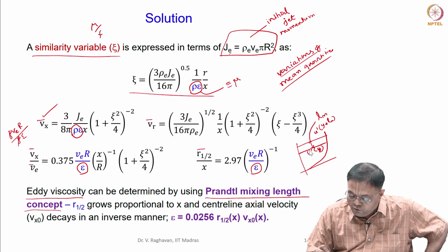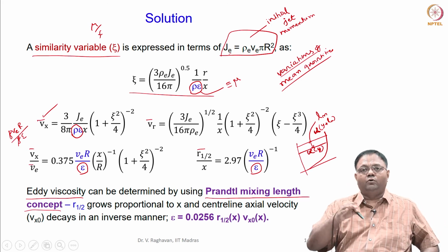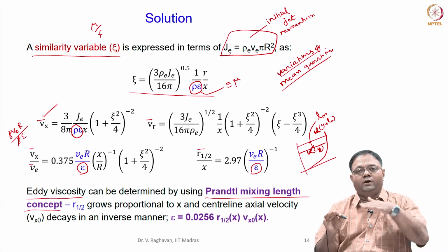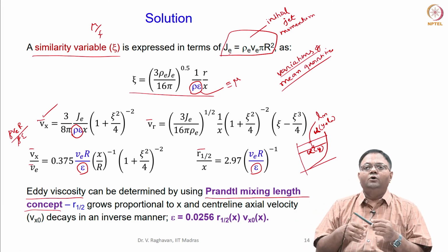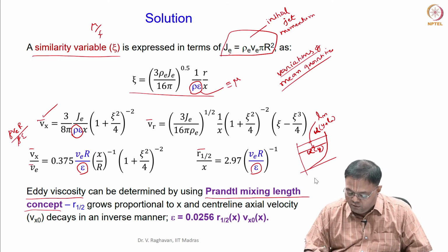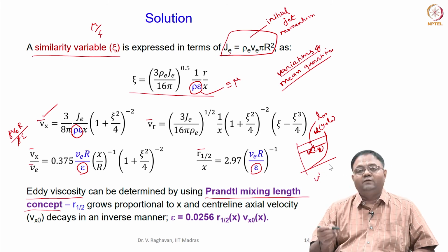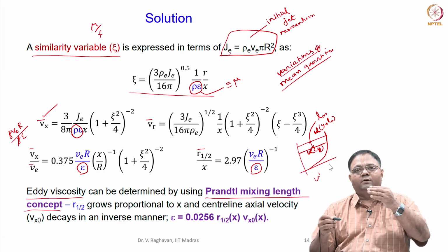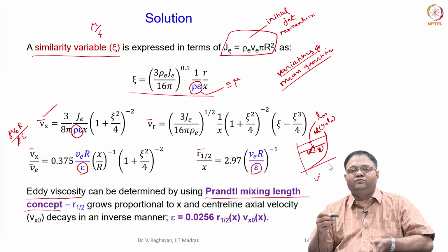Some packets of fluid are going to flow in this direction. I need not put u dash, I say u. These are the layers which are going to flow parallel to the mean quantities, but the fluctuation quantities are going to be there. For example, if there is a v dash fluctuation, then that will contribute to some packets coming across in the transverse direction.